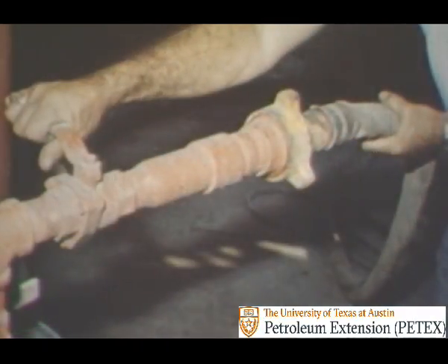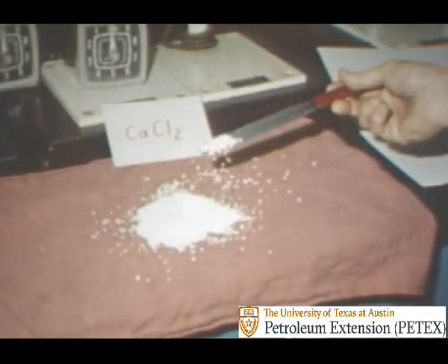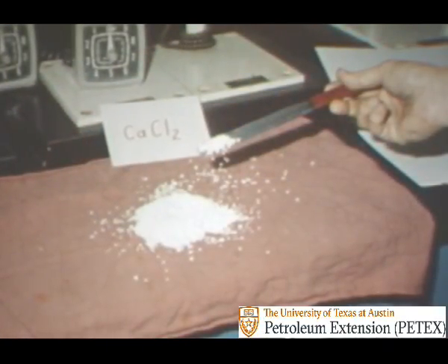A hose is connected to fill a separate tank with water. The water will be mixed later with the diesel oil. It may be brine water that is cut with fresh water to a predetermined salt concentration, or it may be fresh water to which calcium chloride or sodium chloride salt is added. The amount of calcium chloride, CaCl2, in the mud is very important. Calcium chloride is a salt, and it is used to make the water in the oil mud salty.